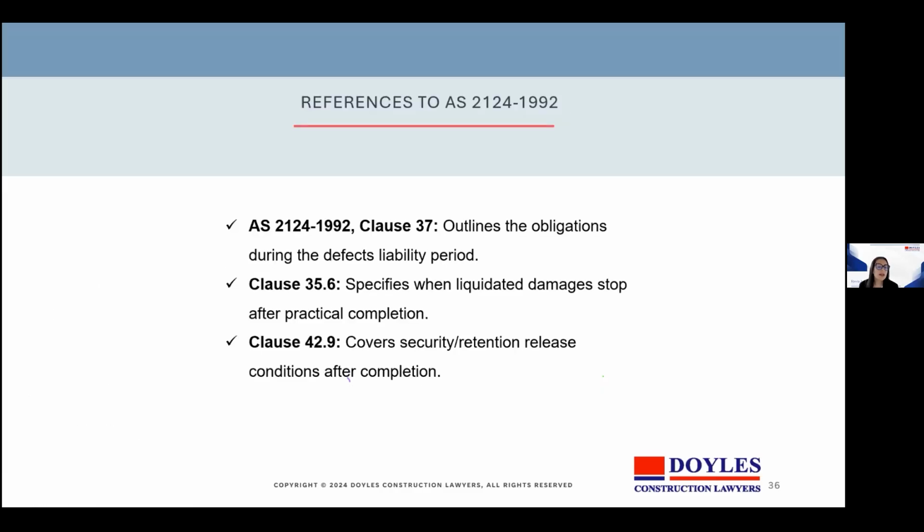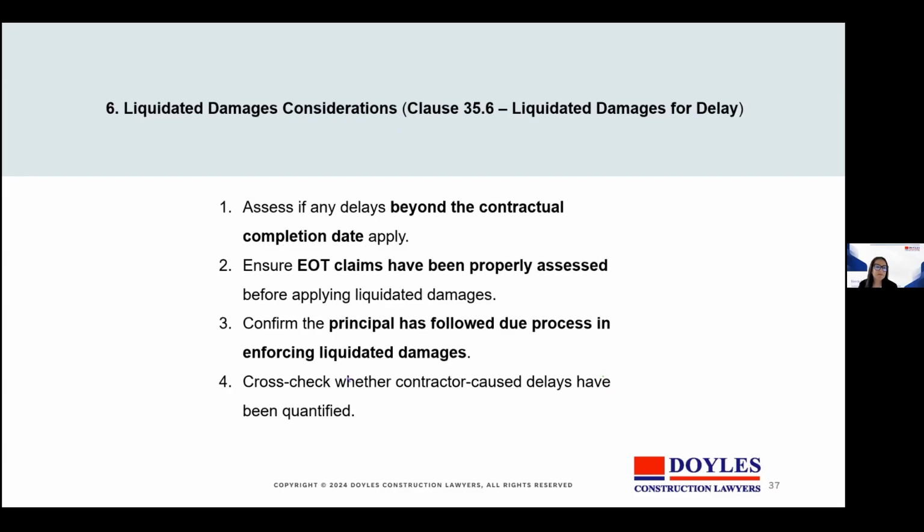Now, just moving on to some of the references in AS 2124. Clause 37 outlines the obligations during the defects liability period. Clause 35.6 specifies when liquidated damages stop after practical completion. And Clause 42.9 covers security, retention, and release conditions after completion. So these provisions ultimately control when the liquidated damages stop and when the rights shift after practical completion.